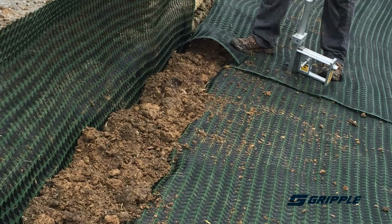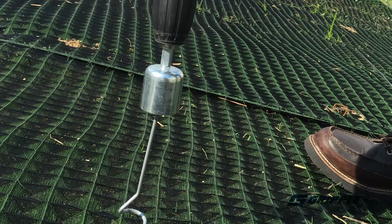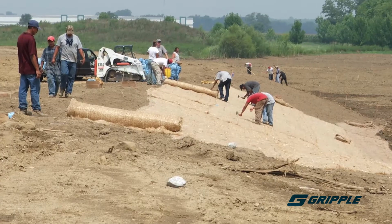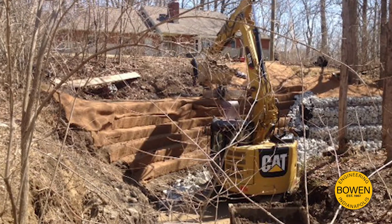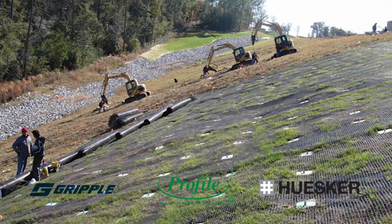How to install. Install per the manufacturer's specification and as shown in the construction plans. The chosen RECP should be applied up and down the slope, never along the contour, and as shown in the construction plans. Blankets and mats must be anchored.